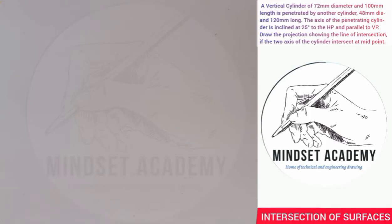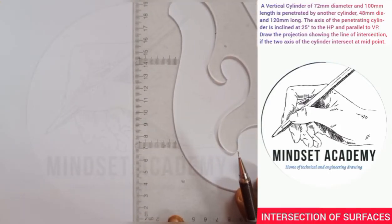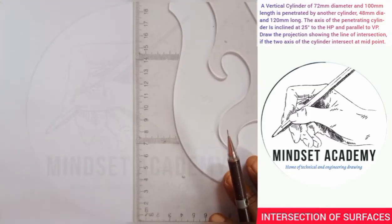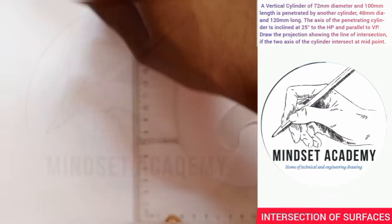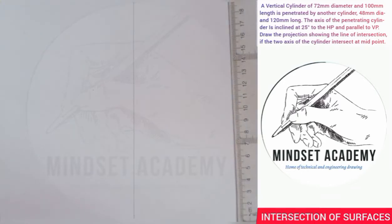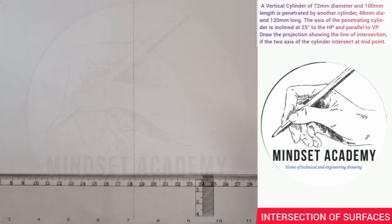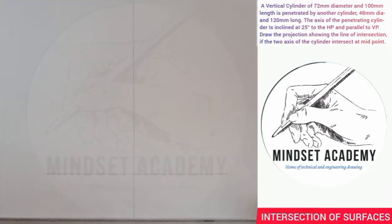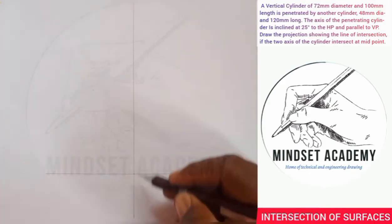Now, the first thing you do when you're doing things involving intersection of lines is to draw the VP and HP, right? So I place my set square on my T-square and I'll draw a vertical line in this manner. Then after doing that, I'll draw another horizontal line in this manner. So we assume that this is the center where the vertical and horizontal line meet.